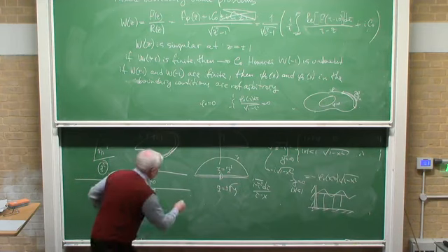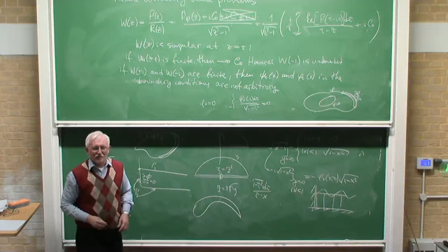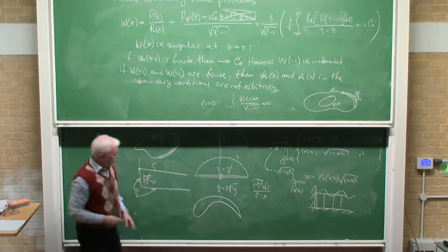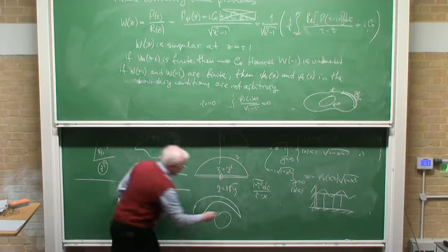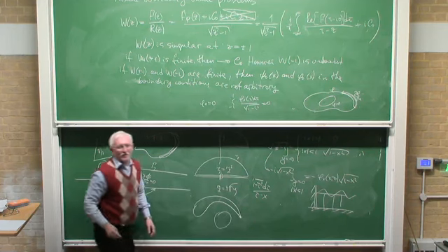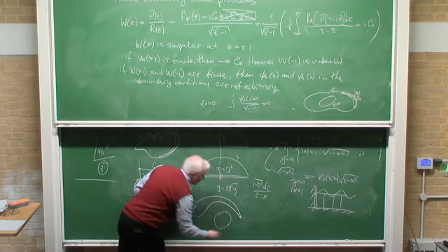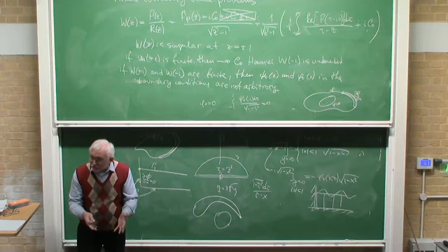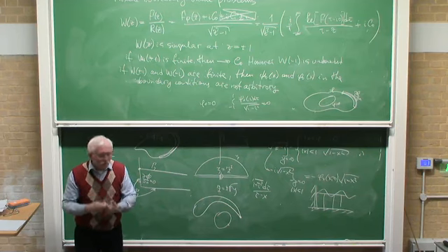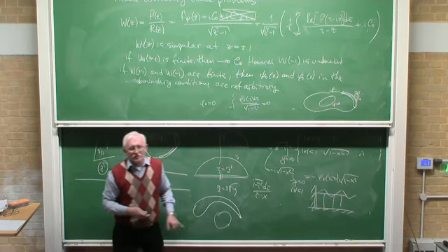But those problems are very much related to the Kutta-Zhukovsky condition. For the Kutta-Zhukovsky condition, that is the aerodynamic profile, and we map it onto the circle, and at that point the trailing edge with a certain angle goes to pi over 2. Then the conformal mapping is singular, but this singularity is used to specify the circulation around.